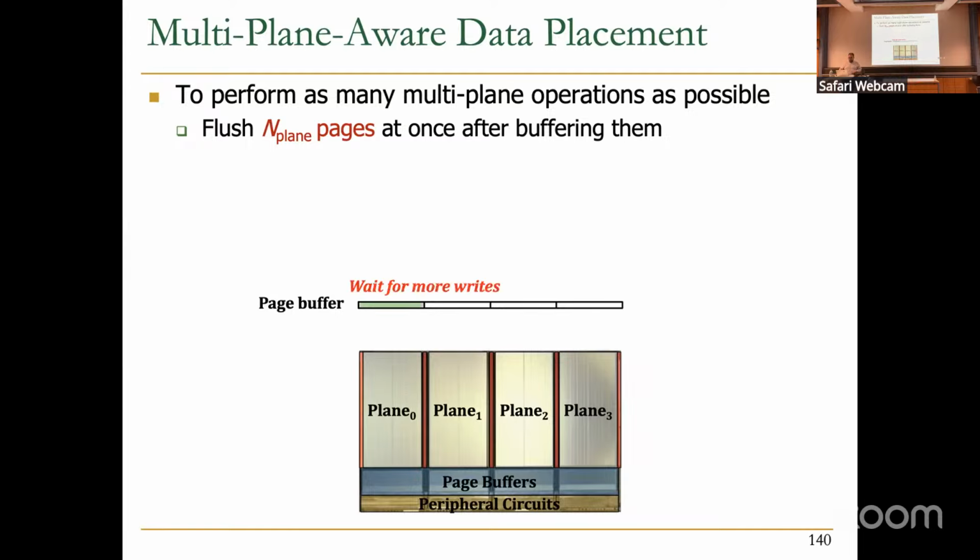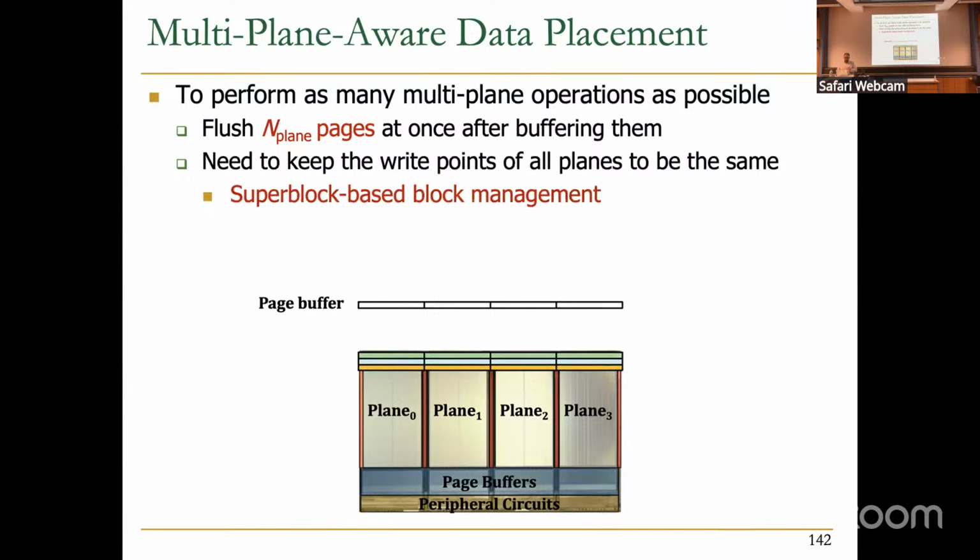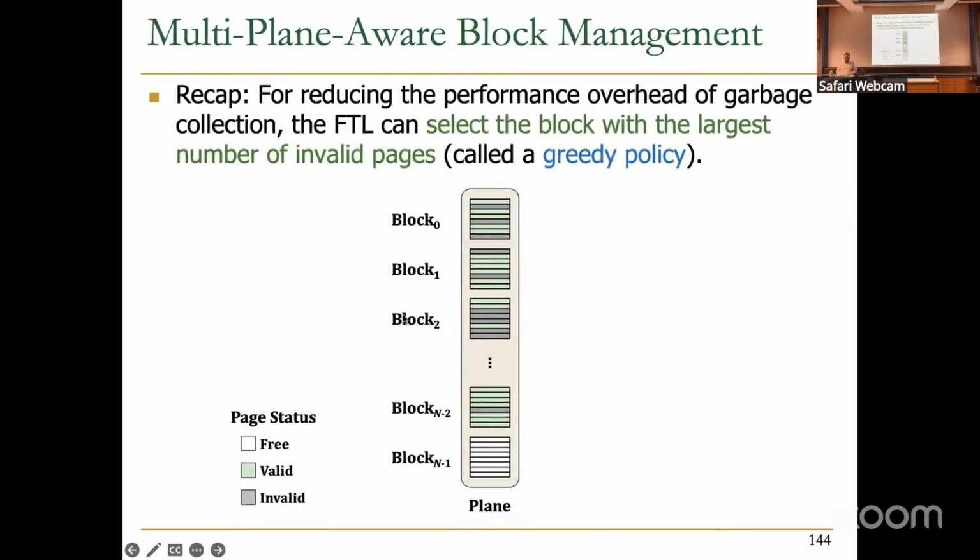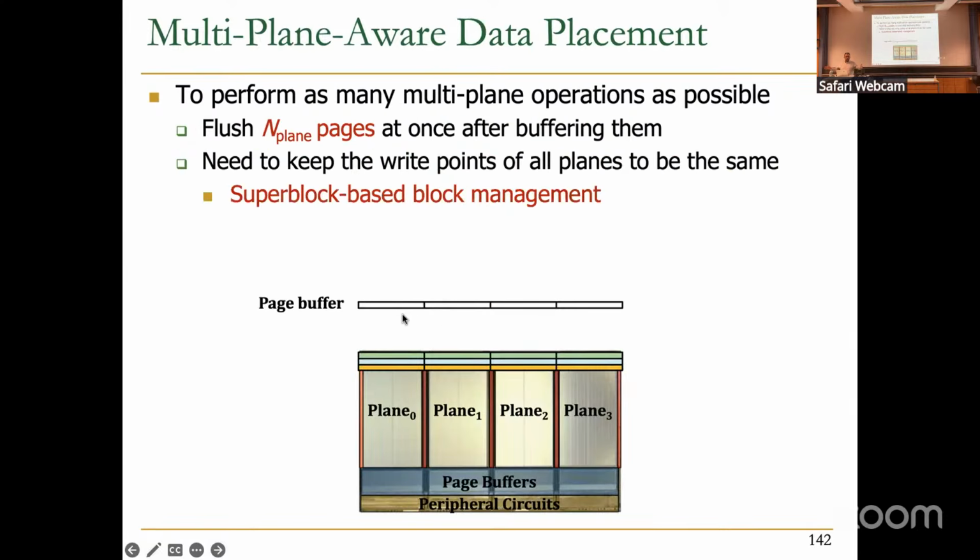Essentially, when we receive a write, for example for one plane, we can wait for more writes and then flush them using multiplane operations. So you can actually benefit from multiplane operations when you're writing. And that's the concept of super block-based block management. It does not need to be only one block. You can have several blocks together and manage them together.